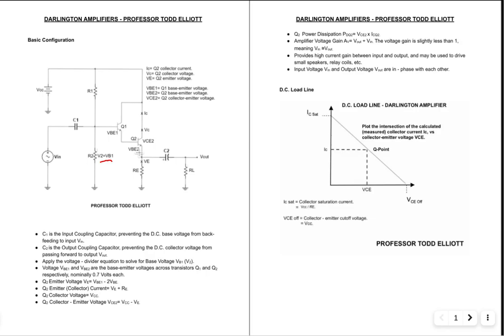And that voltage is determined by the ratio between R1 and R2. Now, as I tell my students, it's a simple matter of picking two ratios on the resistance values of R1 and R2. The trouble is those values impact other things, so they can't be chosen at random, so it's always a compromise. But anyway, we have our base voltage of Q1, which is VR2, okay? VR2.